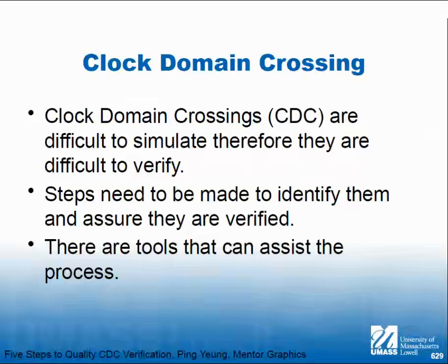Simulators are discrete time devices, which means that a simulator doesn't continuously measure things, it discretely measures things based on the time scale. Remember the time scale from weeks ago. So we tell this thing that the time scale is a picosecond. And whatever your gate level models are modeled at is what you should tell the simulator.